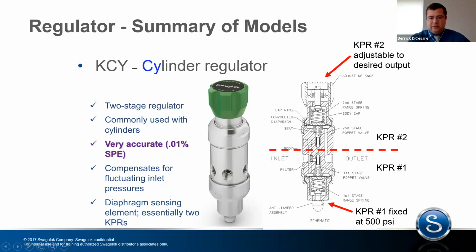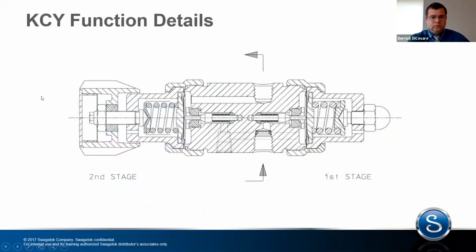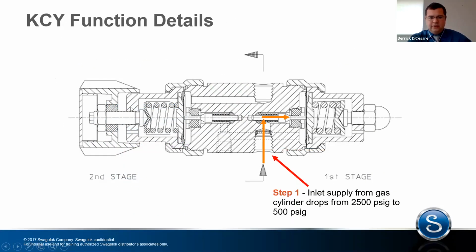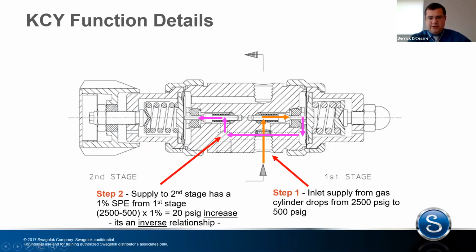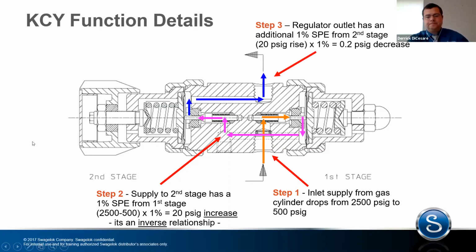It just stays with a set outlet pressure, which never sees the atmosphere afterwards. It's being set ahead of time at 500 PSI, and then it's directly fed into the second stage, and that's the one that we can affect what the outlet pressure is. So again, a little bit of how this works. Your inlet pressure goes in, it goes through a first stage pressure reduction that's internally ported into the second stage. If you buy one of these, you'll see a little port in here that's got a hex plug. That's just to drill this hole into there, into the inlet of the second stage. And then it goes to the outlet.